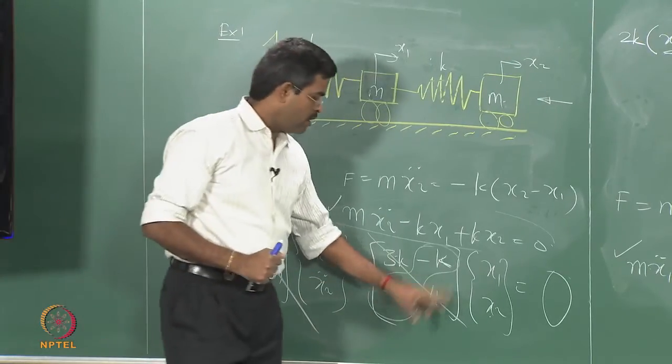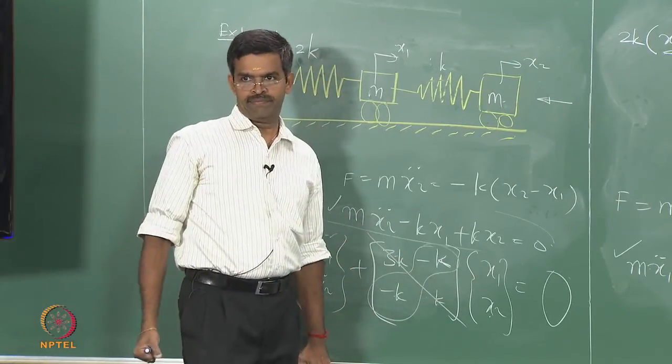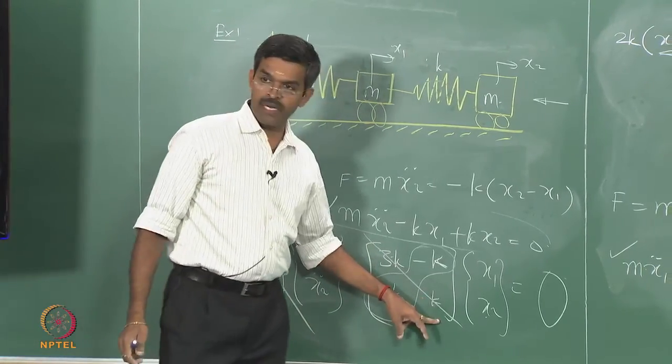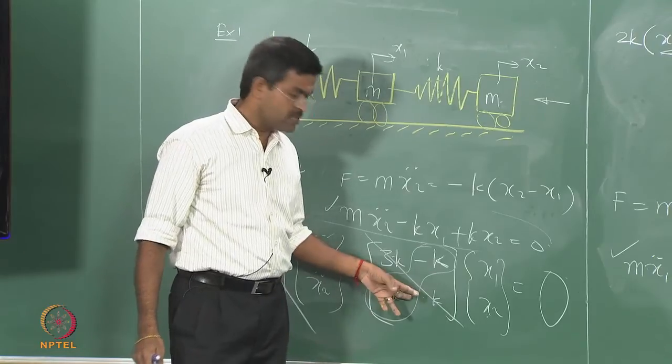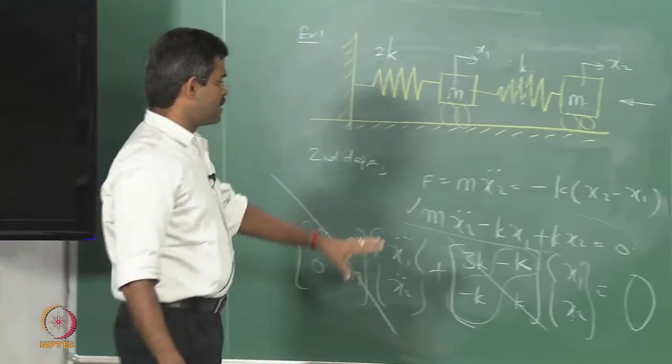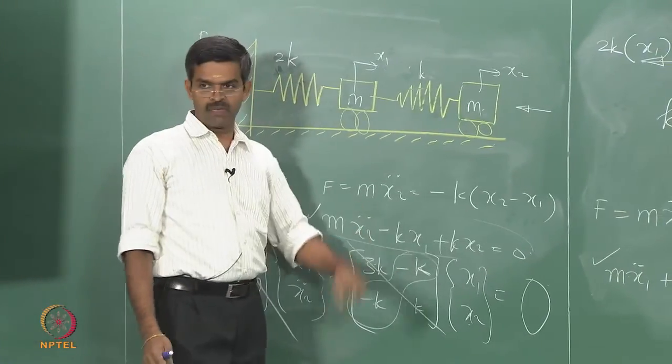It means the values here on any row will be higher. So, these are some checks. If they are not diagonally dominant, you cannot take an inverse. Inverse of this is nothing but flexibility matrix. Therefore, flexibility matrix exists. That is why we get stiffness matrix here.